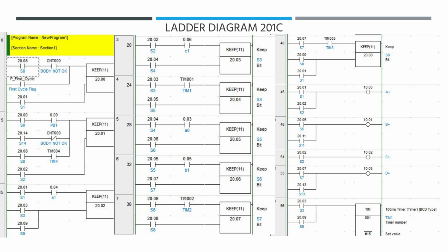This is the ladder diagram for MMP 201. MMP 201 has 14 steps. It has two sets of steps: one for the incorrect position of the product and one for the correct position of the product. For the correct position, it will start from step 1 action. After pressing PB1, it will extend cylinder A.